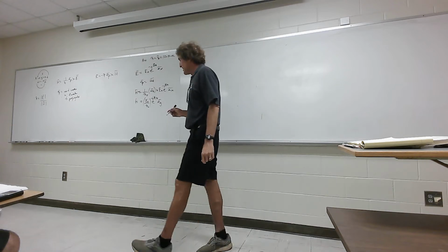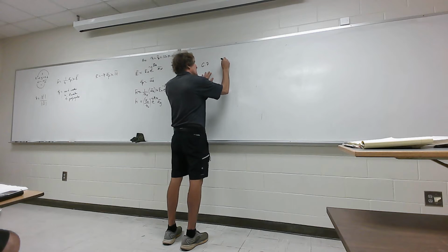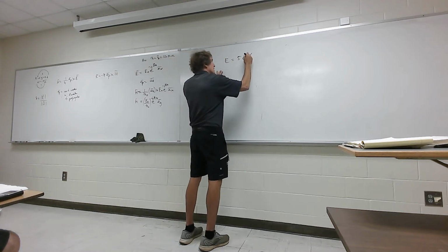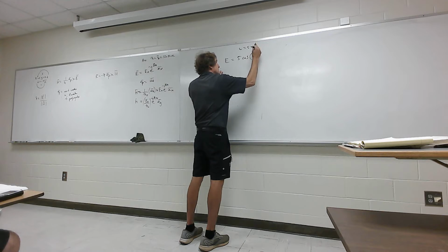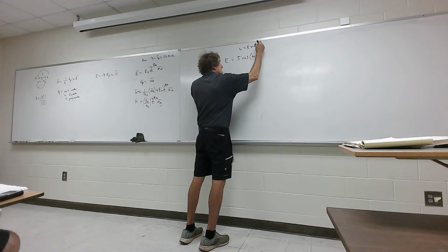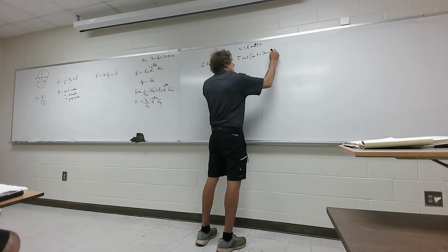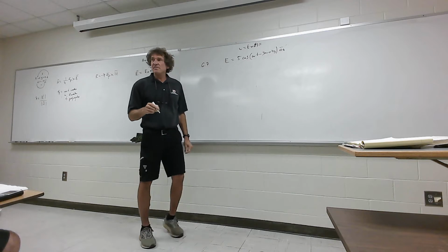6.7? Yeah. Suppose that E of x, y, and t is equal to 5 cosine of pi times 10 to the 6 t. All right, I'm going to just put omega t, and omega is 5 times 10 to the 6, pi times 10 to the 6. Oh, well, this whole thing times pi. Okay. Omega t minus, go ahead. 3x plus 2y, a_z. Yes. It would be volts per meter.